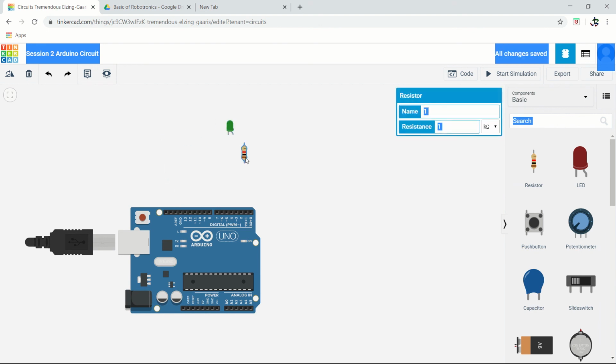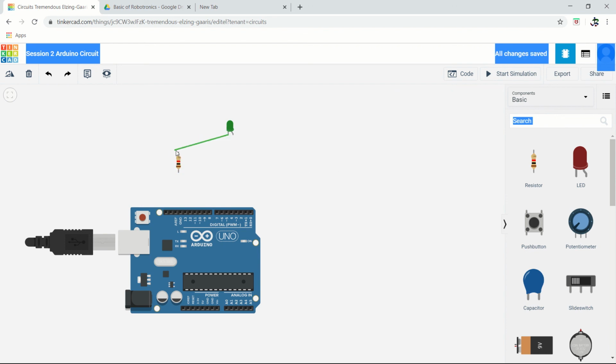so it will not harm anything. At any terminal you can connect it, positive or negative. So the negative goes to the resistor, and that goes to ground, and this goes to 10 number. It is not that the resistor can resist the electrons only if it is connected in front; at the backside also it will resist.